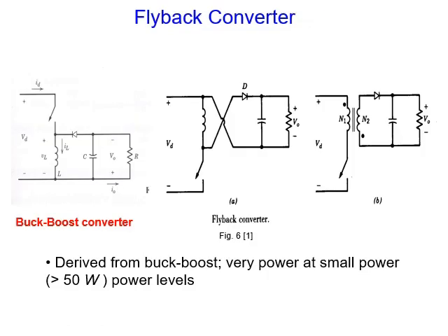Now let me start with the flyback converter. Flyback, actually, what we did, you remember buck boost? We have a switch, we have an inductance and a diode in the opposite direction to that of the buck converter, and energy is stored at the beginning here and released when the switch opens. You remember this? Okay. And we can use it for buck boost, either to have higher voltage than the input or lower voltage than the input.